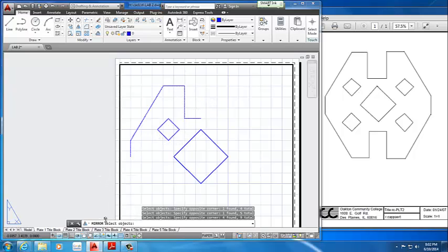So now that's it. So what I type in is enter or space or right click enter. Do not escape. If you escape, you leave the command. If you click enter, you're moving forward with the command. So if it's asking you, do you want to select any more objects? No, I'm good. So you click enter. No, that's it for now.